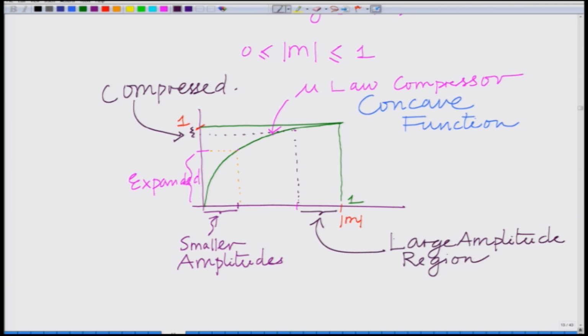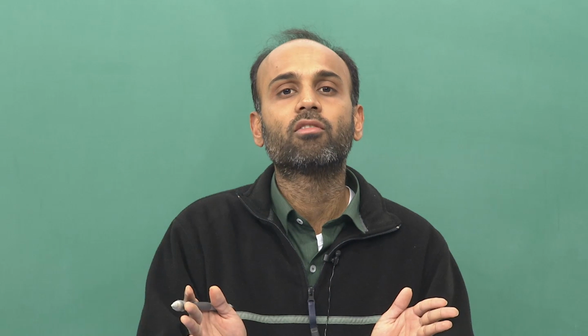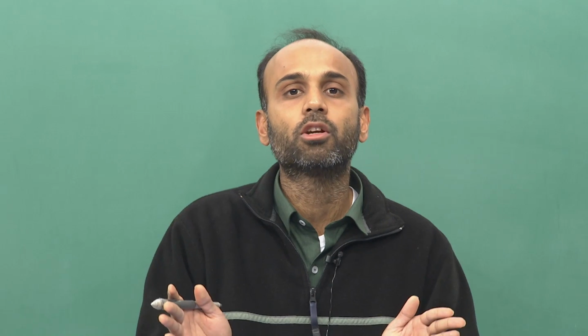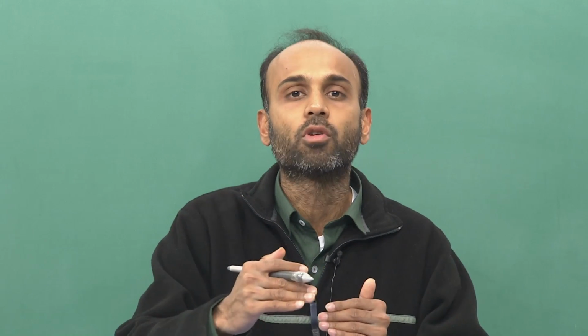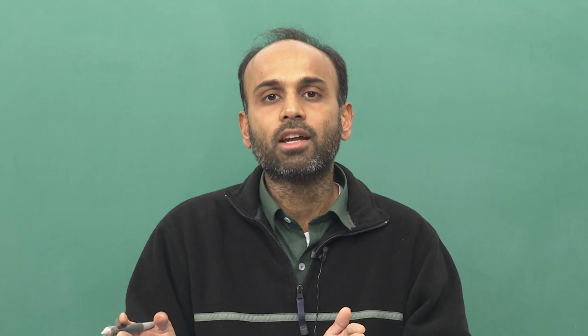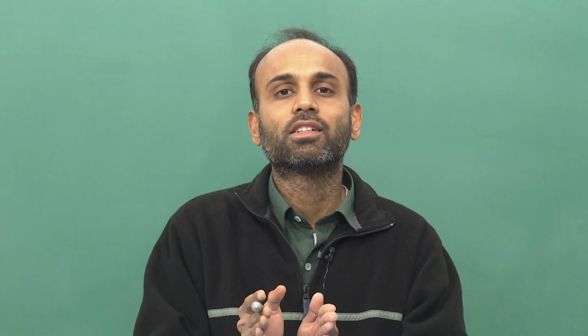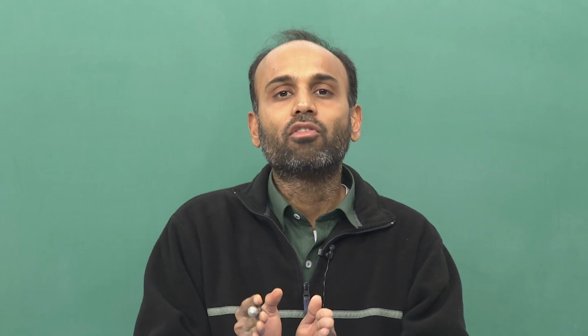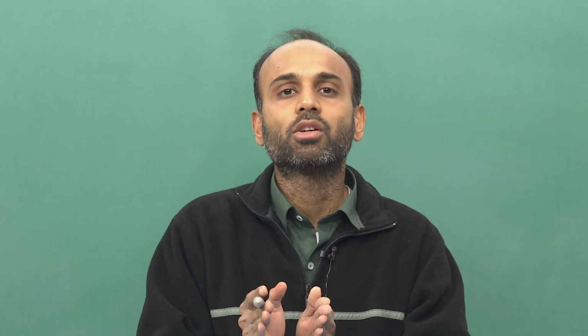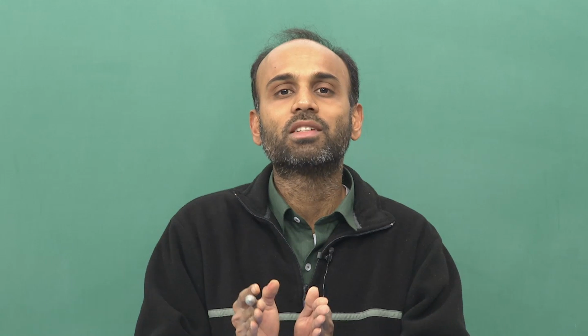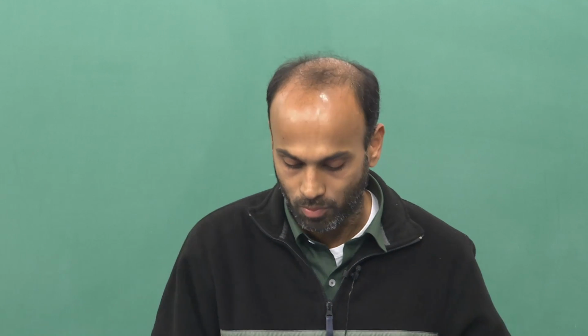So, this expanded region will contain a larger number of quantization intervals, hence it is going to be finely quantized once you quantize the output of this compressor. Similarly, this larger amplitude region, which is compressed to a smaller region in the output, will contain much fewer quantization intervals, and therefore the resolution is going to be much smaller, which means it is basically coarsely quantized. That is the whole point.